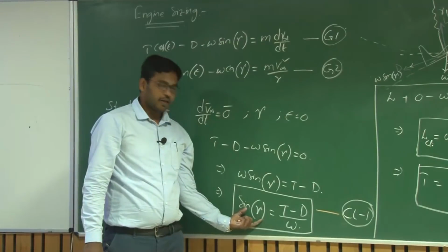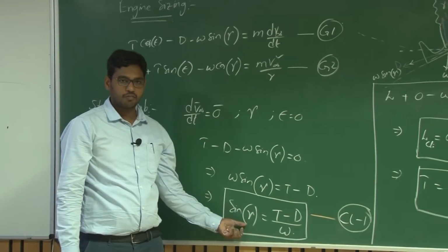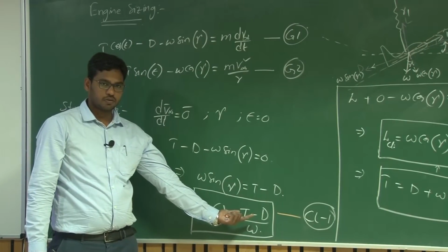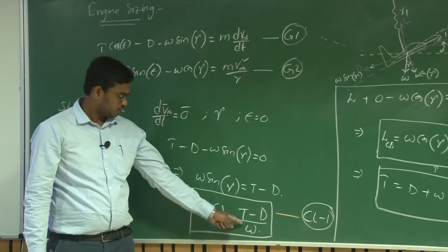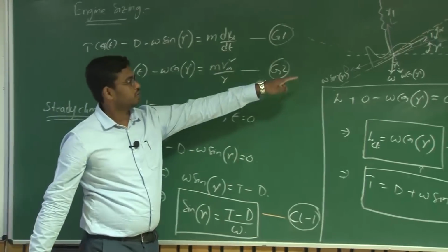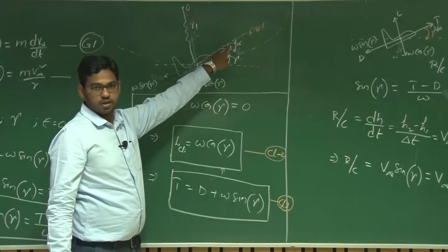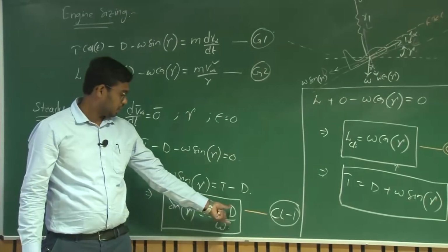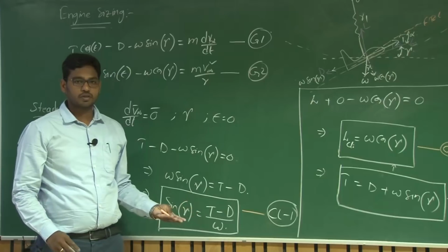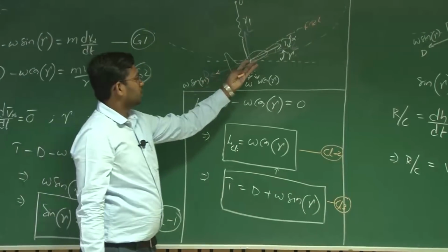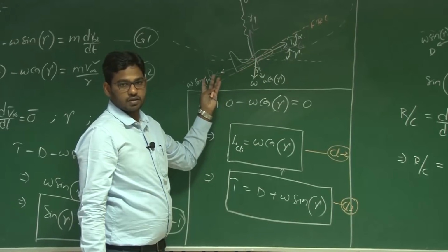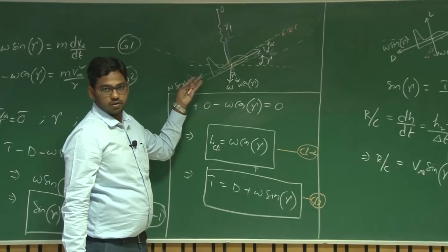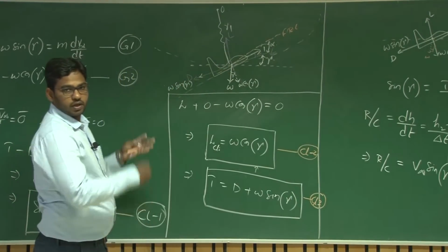If you see, there is a climb. Whenever there is a climb, there is a corresponding climb angle. This is possible only when you have some additional force. T is the thrust supplied from the engine, the output from the engine, and D is a requirement of the system, of this UAV. Drag is the required force; an equivalent opposite force needs to be supplied to the system for a level flight condition.